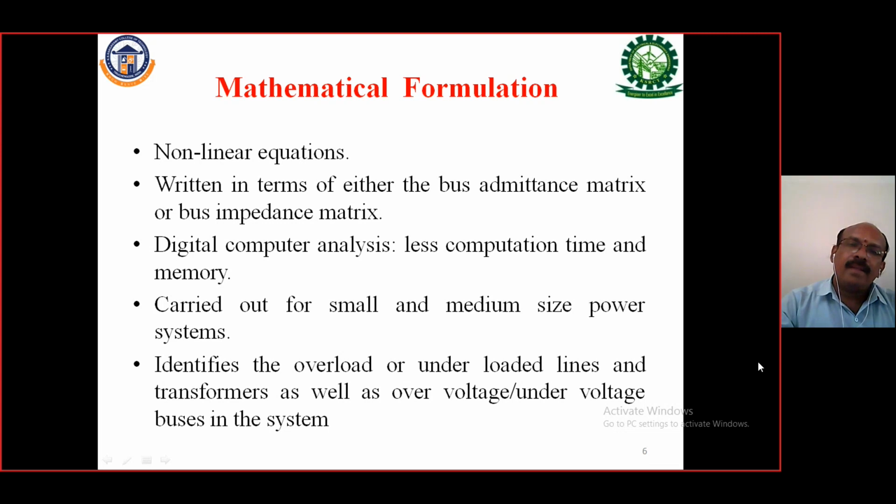Next one is, by using the load flow analysis, we also identify the overload and underload in the transmission lines and in transformers, and we are able to find out the over voltage and under voltage in various buses of the system.